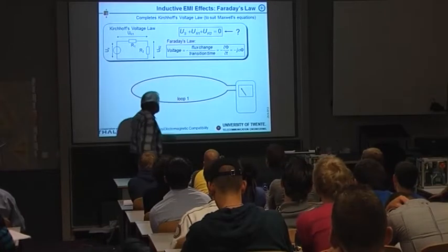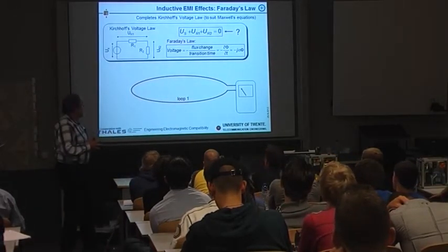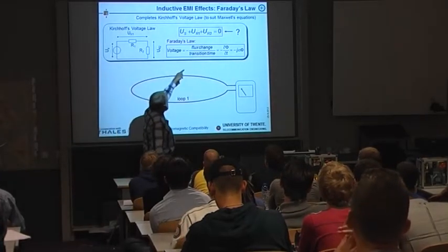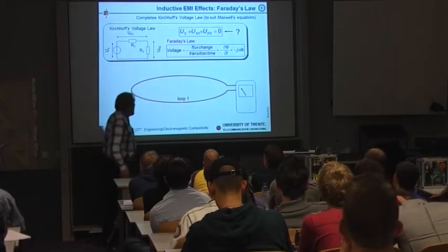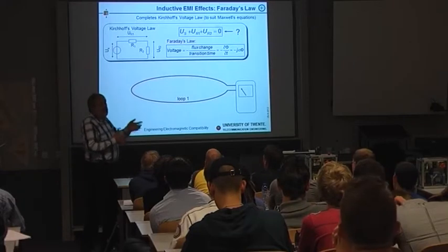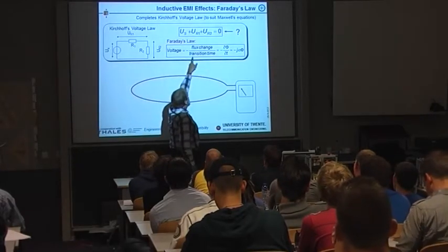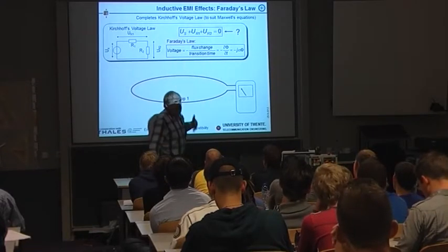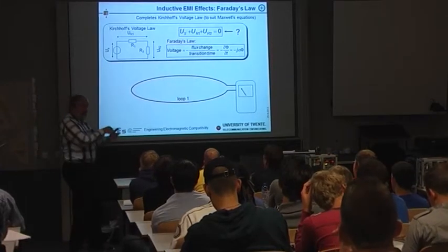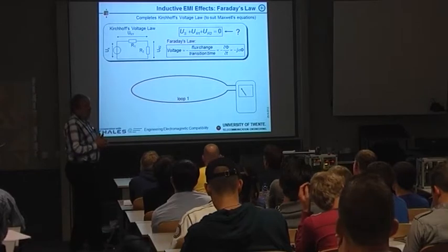Let's say in an old printed circuit board with TTL logic, you had maybe 3 millivolts of noise, being the flux change divided by the transition time. And now everything is 1,000 times faster. Instead of microseconds, you have now nanoseconds. So this is 1,000 times smaller, so the voltage becomes 1,000 times bigger. If you had 3 millivolts in the past, you take the same printed circuit board with a new device, and instead you have 3 volts, and then it probably won't work.